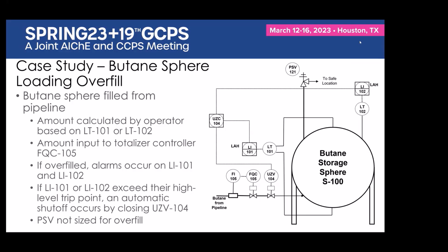Not only do I not see any restrictions, if you look into clause 9 of the standard, it actually recommends that you do this type of analysis. I don't want to delve too deeply in, but clause 9.2.7 says if you're getting SIL 4 or unacceptable risk analysis results, a further risk assessment shall be carried out using quantitative methodology to confirm that the safety integrity requirements are achieved.